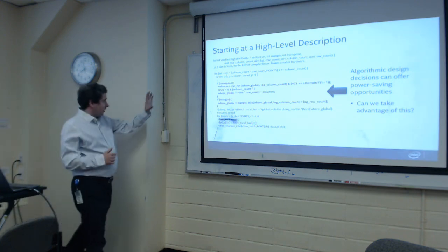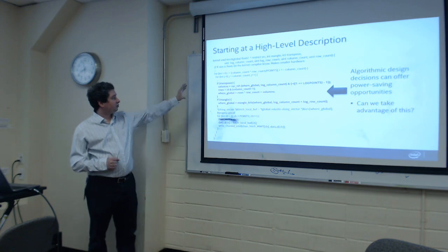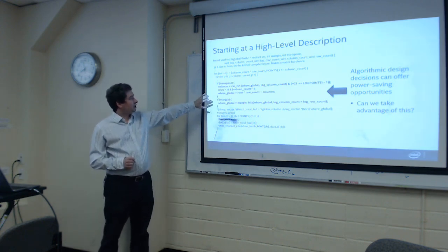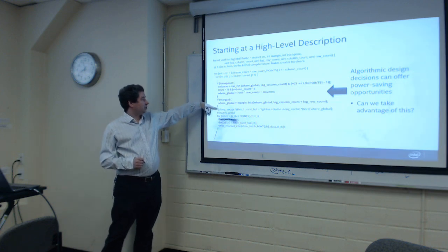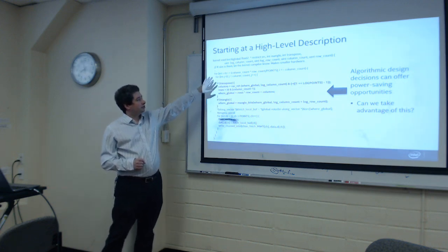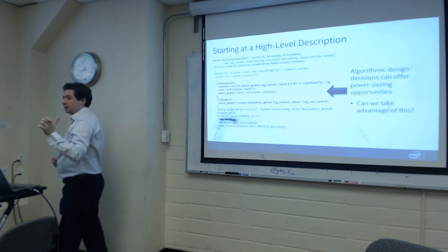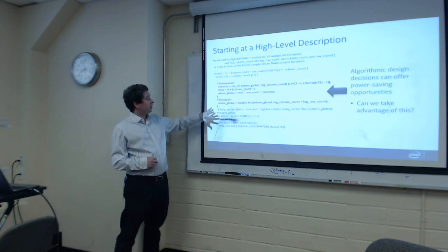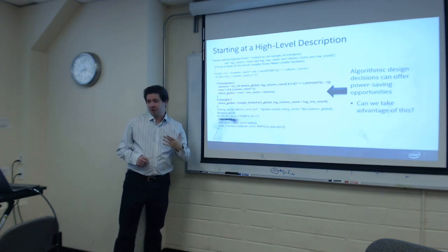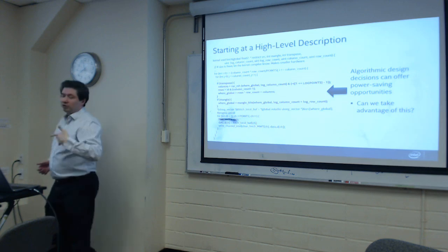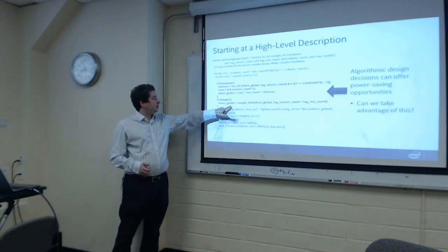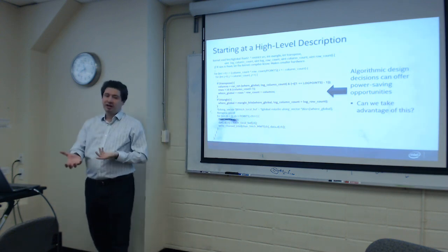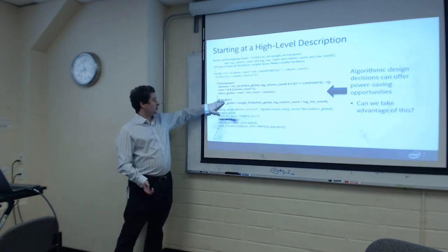So what I did here, and I apologize for a lot of code, is show part of an algorithm, which is actually an FFT algorithm. In that particular case, there are some pieces of code that are triggered by flags that are supplied to a kernel or an OpenCL application. As it turns out, they're sometimes used and sometimes they're not. Now, if you build a circuit that always computes all of the equations in these if statements, then you're consuming power, but you're not getting anything out of it if the transpose and the manual bits are set to 0.